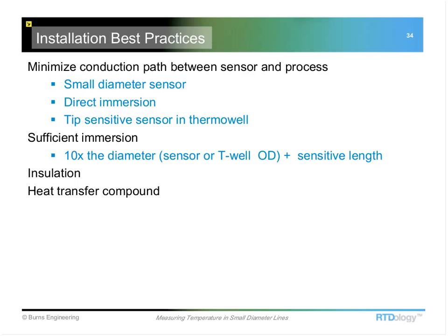Now, this is something that can be used. In some situations, it's not desirable because if you do have a failure, like if it's in a Thermowell, for example, and it breaks, you could get that stuff into your process, and it could be a bit of a headache to get cleaned out of a full system, like in a pharmaceutical application, for example, or some other process where you want to minimize whatever contaminants are getting in there.